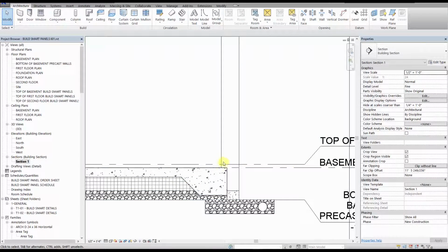Notice that with the slab edge, we have lost a good amount of underslab insulation and now have concrete directly exposed to both the earth and the air. We have a solution for that with our prefabricated J-forms. They are preformed EPS blocks and come in lengths up to 8 foot, and they pull double duty as both a thermal break and a form for pouring and casting your thickened slab edge against.